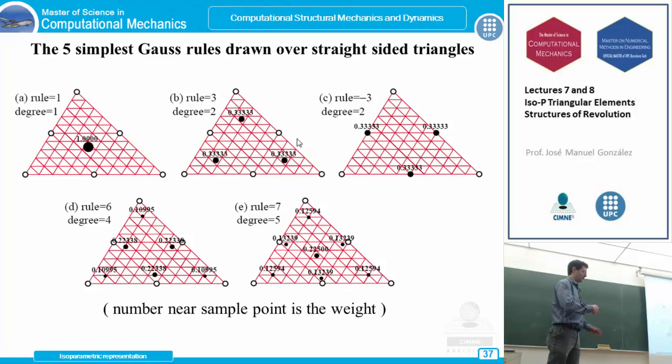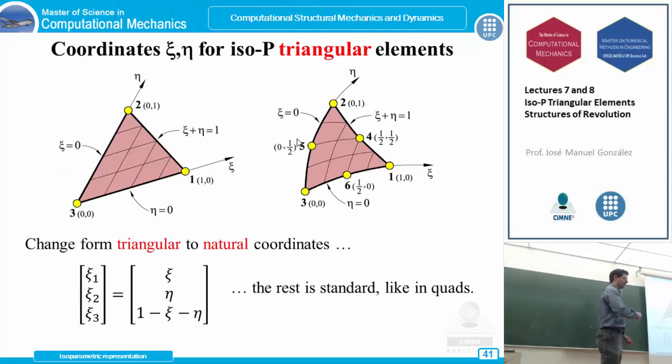Okay, so now numerical integration takes place using the same idea, the same double summatory with the weights and with the evaluation of the f function using the strain displacement matrix, the elastic matrix, and the Jacobian value. All of them are evaluated in the natural coordinates, so we must make a change of variable using the Jacobian matrix, using the partial derivatives of the Cartesian variables, as we have seen with the quadrilateral elements and in the general theory.